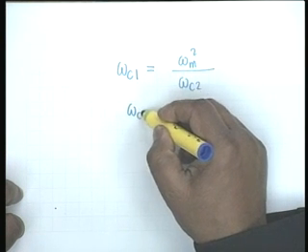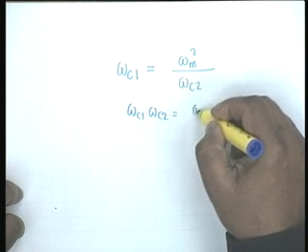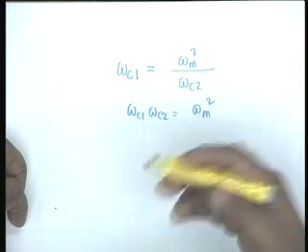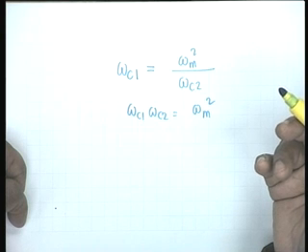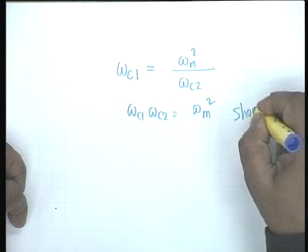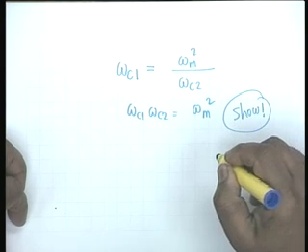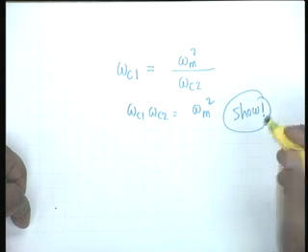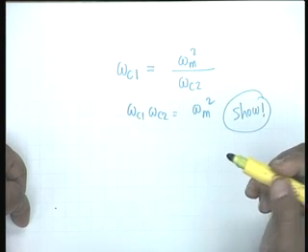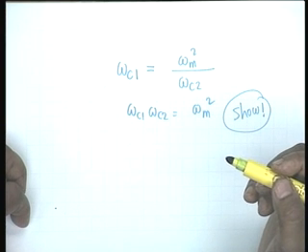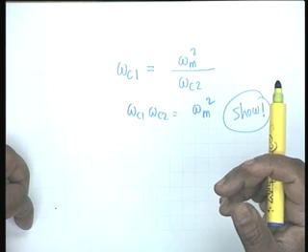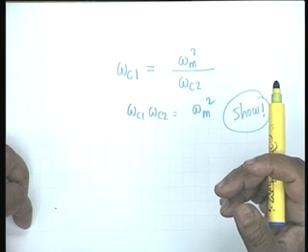That is, omega c1 times omega c2, the product, is equal to omega m squared. If one is greater than omega m, obviously the other must be less than omega m. Okay? Now let me put this as a problem to you. This relationship, that is the product equal to omega m squared, is described in mathematical terms, in geometrical terms, as a symmetry.